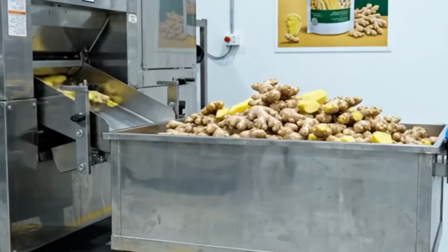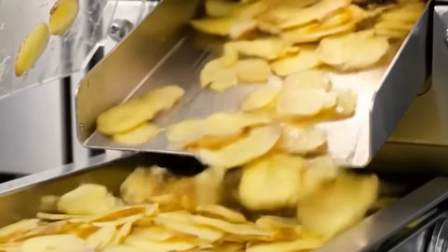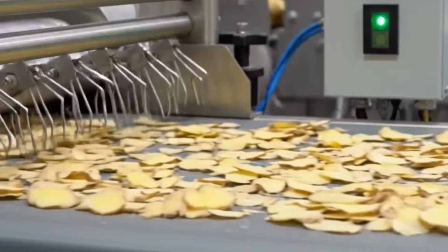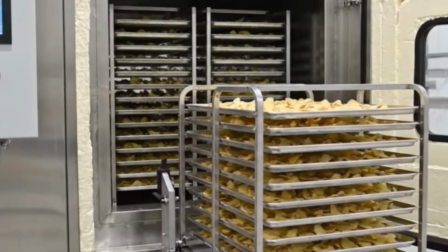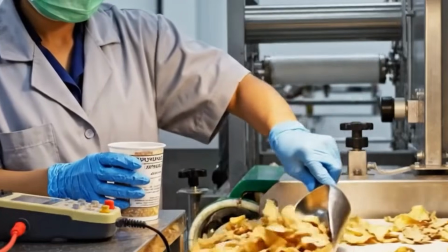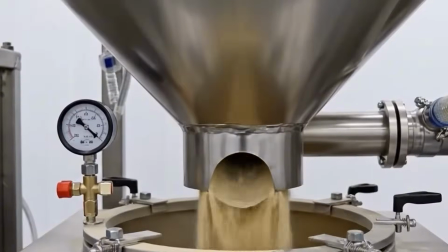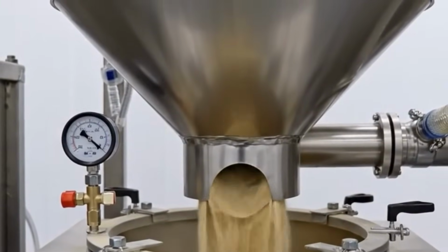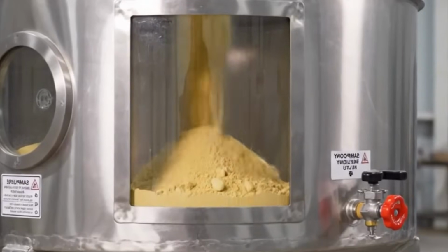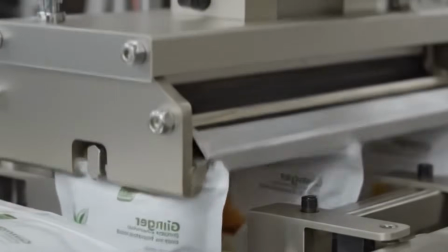Filled and sealed containers are conveyed through a vision inspection system equipped with high-speed cameras and LED backlighting. Algorithms analyze fill height, cap placement, and label orientation. Infrared sensors check for proper internal pressure via deformation profiles. Containers that do not meet specification are removed from the line using pneumatic pushers.